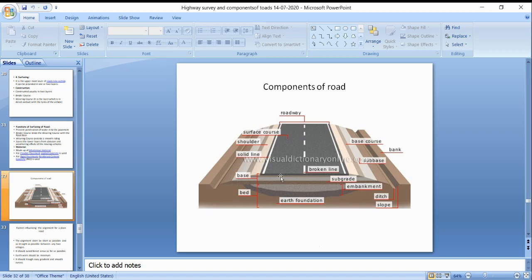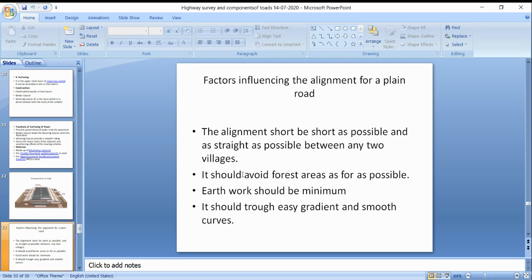Here we have seen this is the carriageway or roadway, or surface course. Next comes the binder course in between the base and surface course. We are seeing the binder course here, and here the subgrade. This is the subgrade here. If a subbase is put, some layers will be there, or will not be there. The subgrade, the base course, and this is the wearing course here.